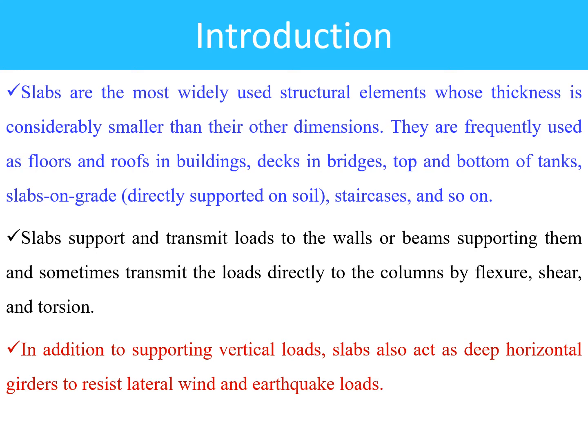Slabs support and transmit loads to the walls or beams supporting them. Sometimes they transmit the loads directly to the column by flexure, shear and torsion. In addition to supporting vertical loads, slabs also act as deep horizontal girders to resist lateral wind and earthquake loadings.